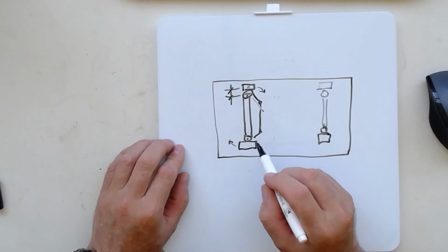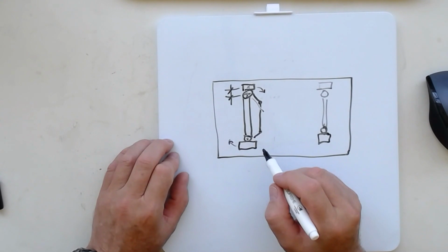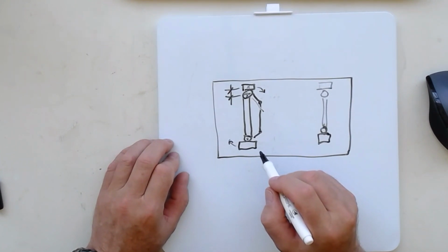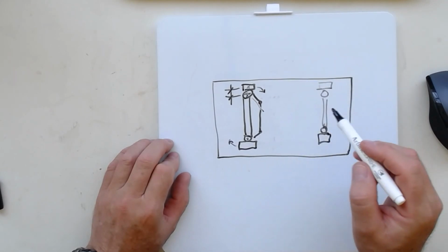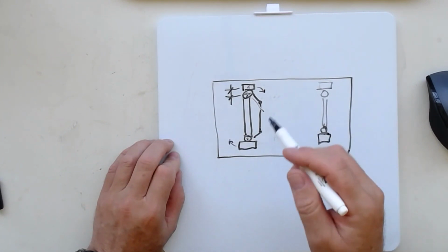It's a case of whether your steering effort is greater than your traction. It's the reason in your car when you're perhaps pulling out of a tight parking spot and you need to steer quickly, you can't do it with your brakes full on. You might still have a little bit of brake, but not full on. So you build a vehicle, put the brakes on, and you realize it won't steer. Don't be surprised. That's the reason.